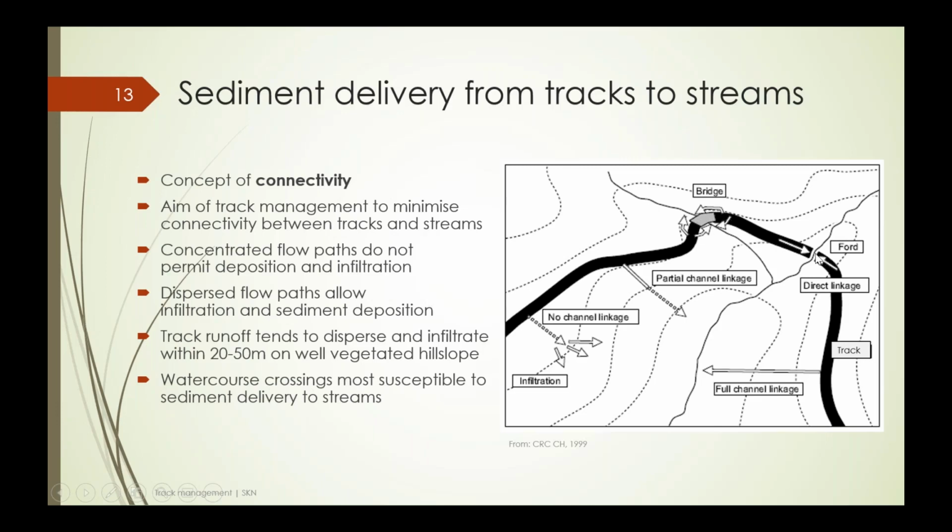These are situations where considerable effort is needed, first of all, to make sure the structure is safe, but at the same time, there are also conditions in the code to try and minimise the amount of sediment running down the road and connecting with the stream. And the particular condition requires that you have a structure to direct runoff off the road somewhere between 5 and 30 metres from the drainage feature.